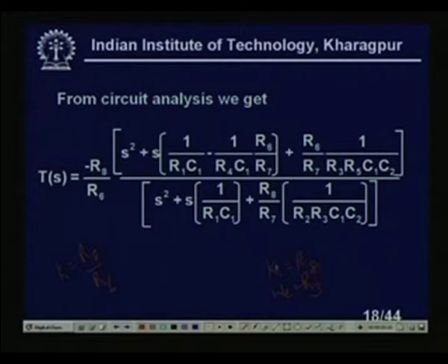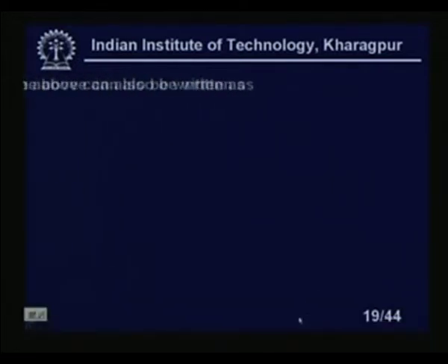Similarly, you see that once K is tuned, now I am choosing R3 to tune omega z. What is omega z here? You see it is omega z. Now, this also will vary during that time, it does not matter. I will choose some other elements later on to get the omega p exact desired value. So, that is the reason I am telling you that particular sequence you have to maintain, otherwise there will be a problem. Now, you see, once I have chosen R3 to tune omega z, I am not using R3 anywhere else to tune any other elements. I will choose some other elements to tune omega p or qp like that, right. So, that is the case that I want to explain to you.